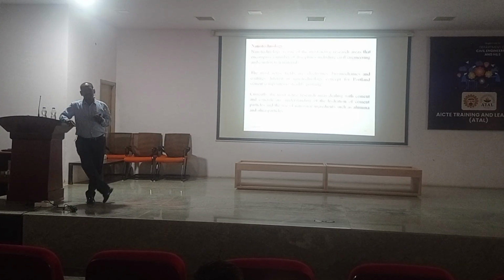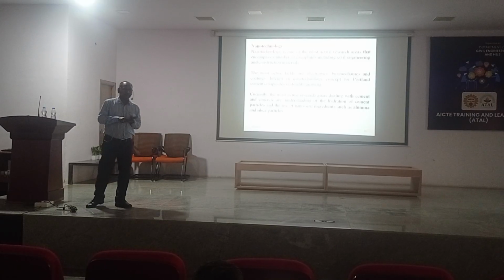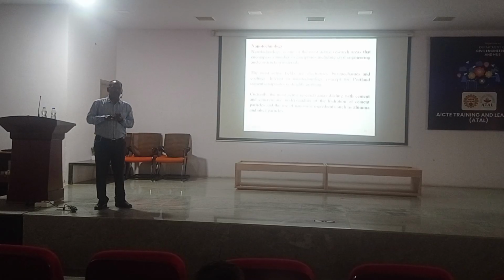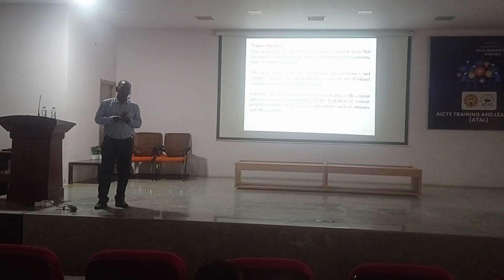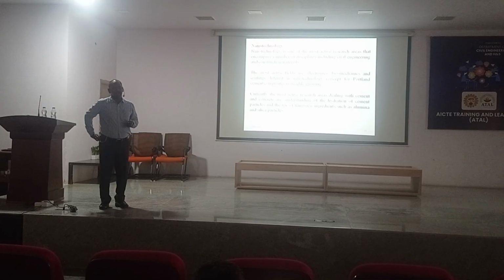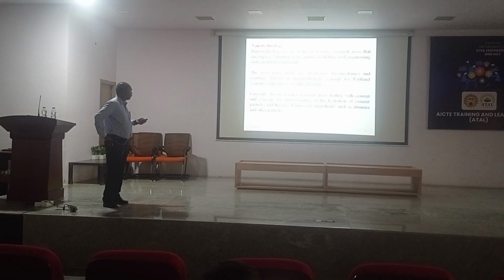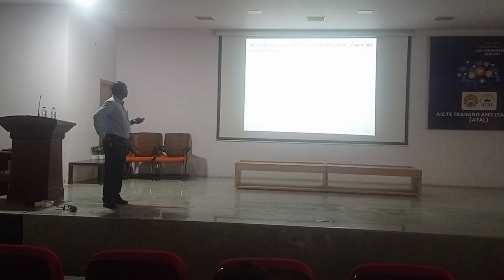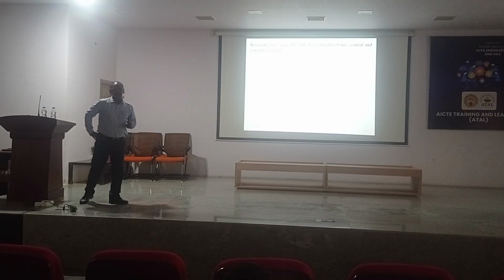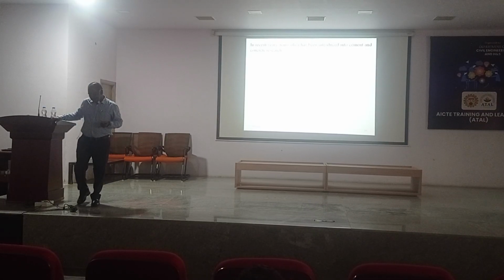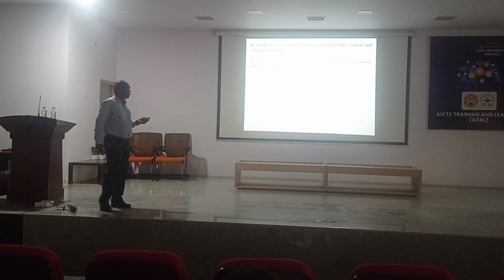That's why there are so many tests. You can check heat flow, hydration, and you can conduct thermogravimetric analysis, TGA, DSC. Based on that, you can show which material is more prominent. Nanosilica has been introduced to cement and concrete, and many scholars are using this nanosilica.